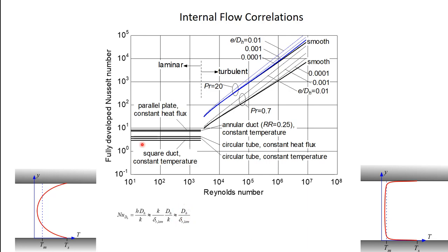And you can see, if I go up here, this is a number that's not that different than 2 or 3 or something like that, depending on the duct shape. So how far I've got to conduct energy for a laminar flow depends a little bit on the duct shape, right? Because I can smush this temperature gradient out or stretch it, but in the end, it's pretty much dictated by the duct shape. It doesn't depend at all on the Reynolds number, though. Not once you become fully developed, and it doesn't depend at all on the Prandtl number, right? It's a geometric quantity from that standpoint.